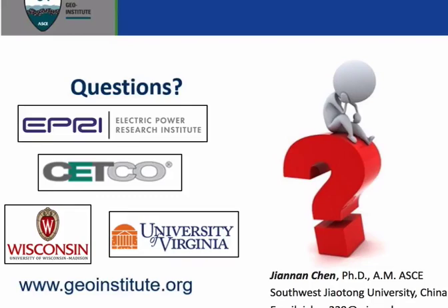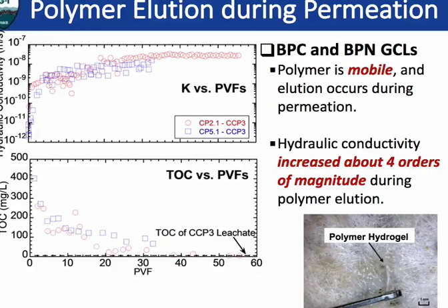That's an interesting question. So, this leads to our future work, and we are exploring the mechanism more deeply. Right now we run the test because there's an obvious increase in the hydraulic conductivity of the GCL. It shows an increase of 4 orders of magnitude of the hydraulic conductivity, and we correlate this to the TOC, and we'll do in the future to see the low hydraulic conductivity GCLs. Yeah, for sure.